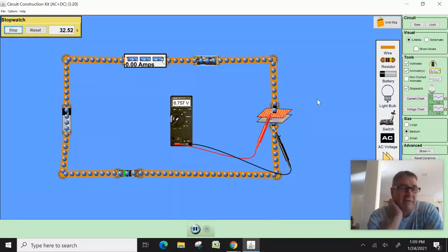And that's what I mean by after 5 RC, where the RC here is 10. So after 50 seconds, it's pretty much done doing what it's going to do. And you'll see when it gets up to 50 seconds on the clock, this will be pretty close to 9 volts. I'll stop it, even though I didn't start it at exactly the right time. You get the idea. So let's run a little bit longer.